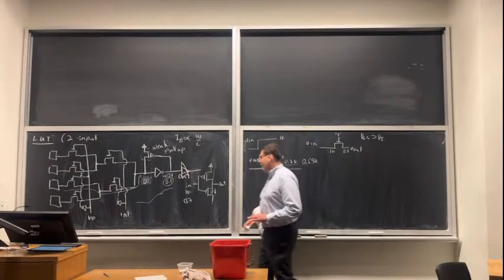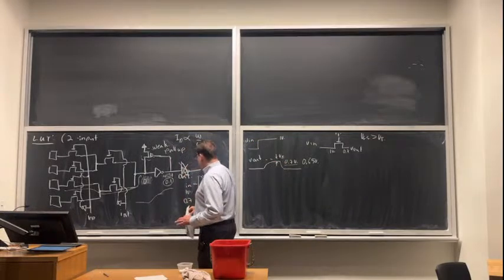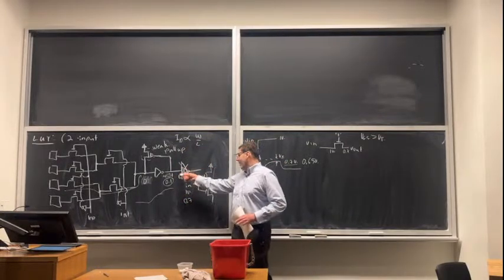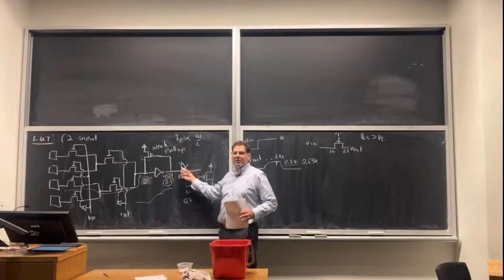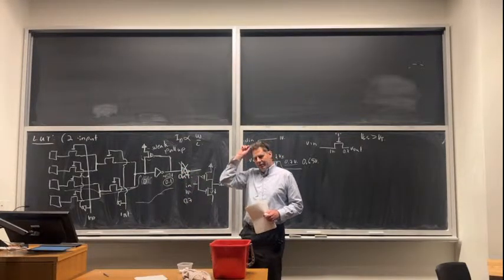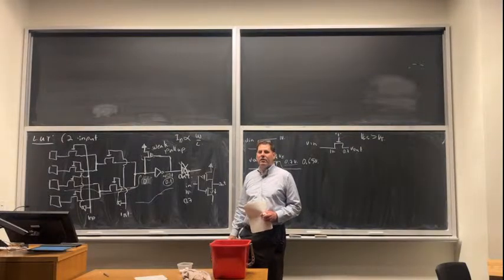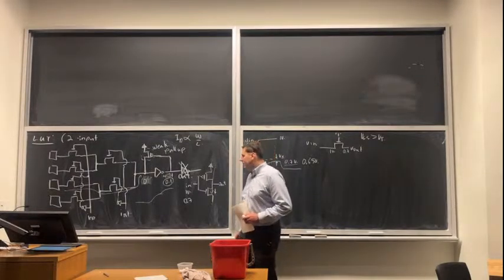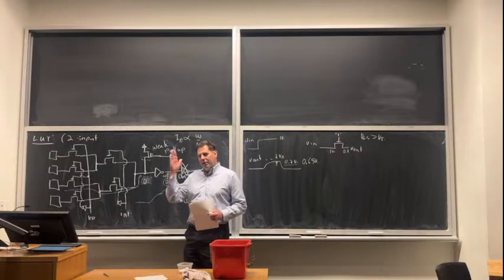I'm not going to do it in this analysis because I'm just trying to keep it simple. But often there is a second inverter here. In fact, usually there is. I always saw designs with a small inverter and a bigger inverter connected together. So that's a common technique because you're trying to increase what's called the stage ratio.